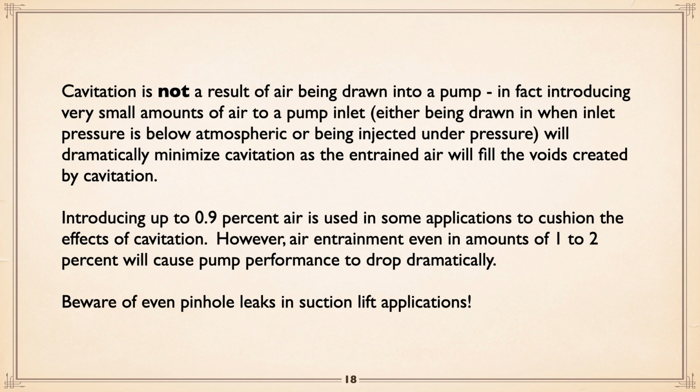There was a pump station in Vancouver that had cavitation issues, and they actually did have a compressor that was putting in small amounts of air. And the effect of that is very dramatic, by the way. Instead of growling like hell, virtually the pump will go silent when you get that air in there.